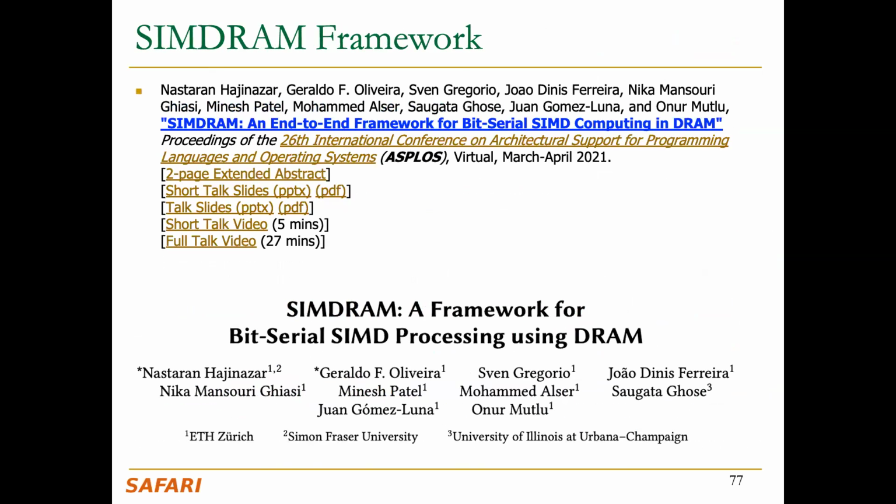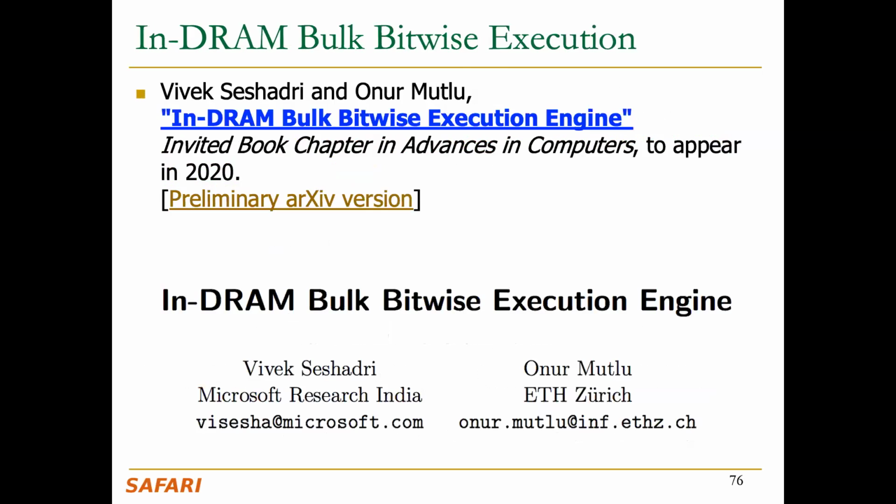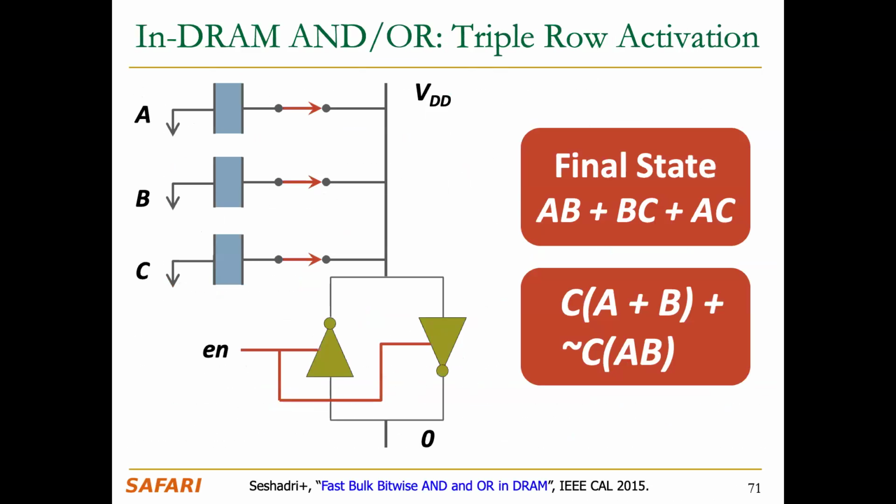Any questions? Yes, please. The signal to noise. From the signal to noise point of view, you have 8,000 of these capacitors. Will the output be reliable? Can you trust that you always give the correct result? So it's not the number of capacitors, but it's the variation across the capacitors that actually leads to a problem. The number of capacitors doesn't matter because all of them operate independently. There's another copy of this over here, another copy over here. They operate independently. But if there's a lot of variation in the size of the capacitors, then you may not get the bitwise majority function. And that's a very good question. You really need to keep variation under control.